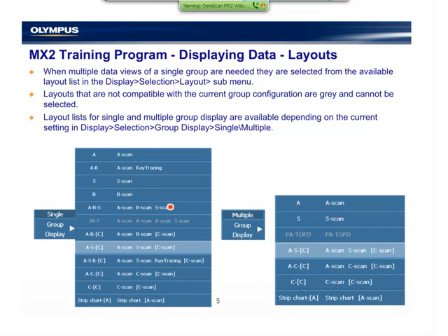But the phased array is most associated with the S-scan or sector scan type of display. When using the multi-probe or multi-group type of inspection, there's a smaller, more limited display that shows us views that can be combined with multi-probe and multi-group inspection, again combining the traditional A scan with the phased array sector scan.